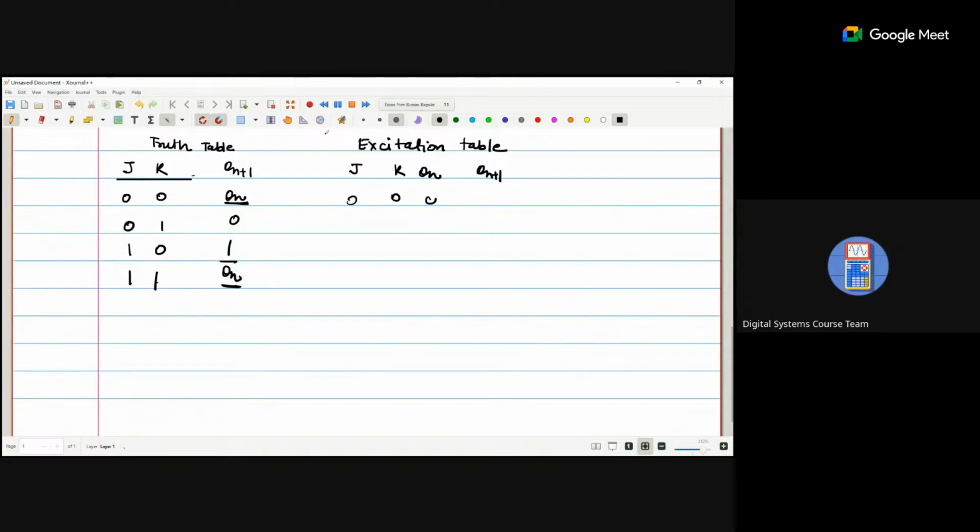0 0 0, 0 0 1, 0 1 0, 0 1 1, 1 0 0, 1 0 1, 1 1 0 and 1 1 1. Now, what is Qn plus 1? If JK is 0 0, that means these two cases, Qn plus 1 is Qn.